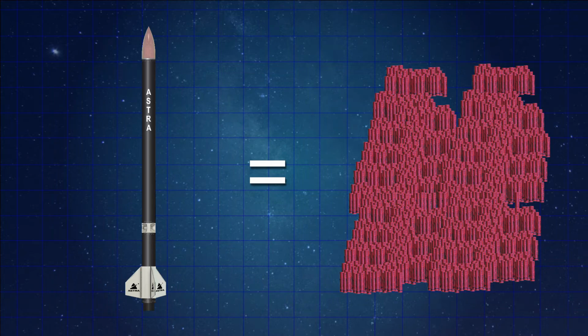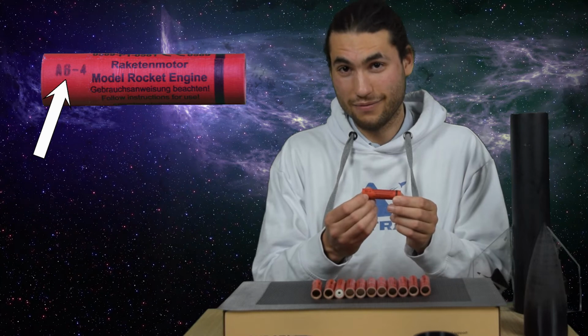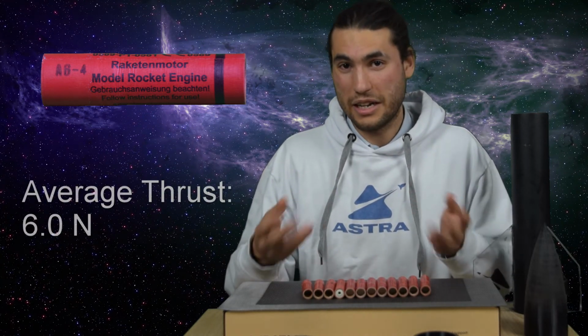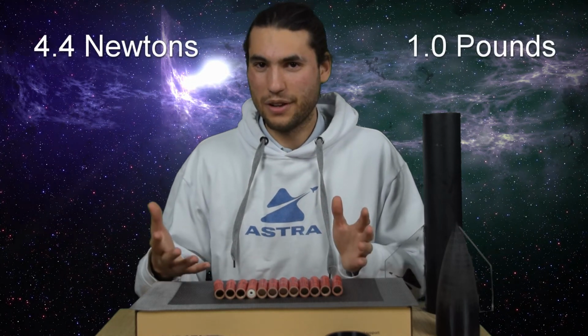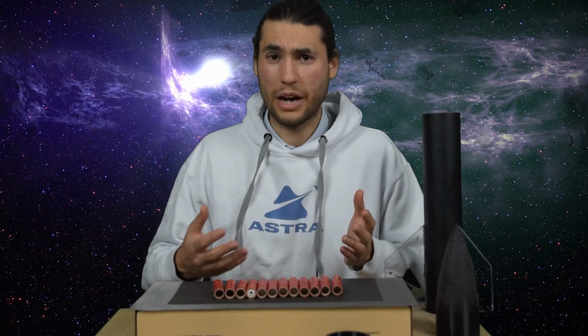The next part of the code is a second digit, which is always communicated right after the letter, and that is telling us what the average thrust of the rocket is in newtons. And for those who are in America and don't know what a newton is, about 5 newtons makes 1 pound. So you can just divide any newton value by 5 and then it'll tell you how many pounds of thrust it's delivering. And of course, we have to remember that this thrust is an average thrust.